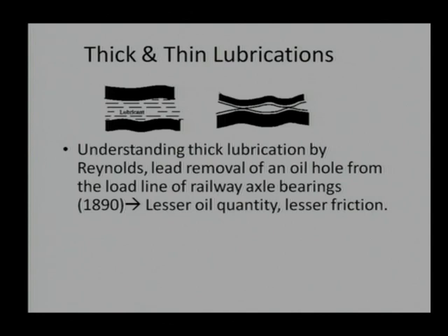If I go ahead with this theory, we say that thicker and thicker lubrication will not be very useful. If I keep on increasing the thickness of a lubricant, it will not be very advantageous to us. A lesser quantity is causing lesser friction. Of course, there is no wear. This is the mechanism where there will not be any wear, but there will be only friction. If we provide more and more lubricant, there will be more and more friction. So, to find out what should be the optimum value of lubricant thickness, we need to use Reynolds theory, we need to use this kind of solution.